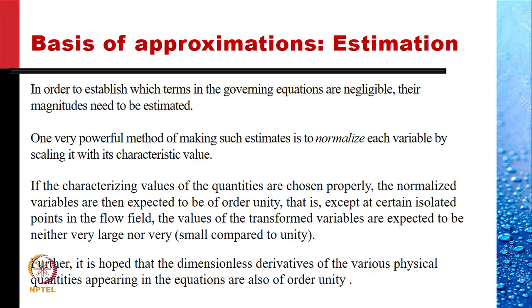And we start with the approximations of the governing equations. In order to establish which terms in the governing equations are negligible, their magnitudes need to be estimated. One powerful method of making such estimate is to normalize each variable by scaling it with its characteristic value.